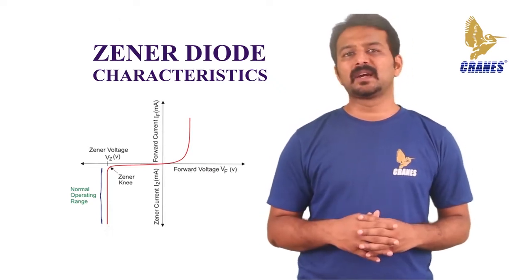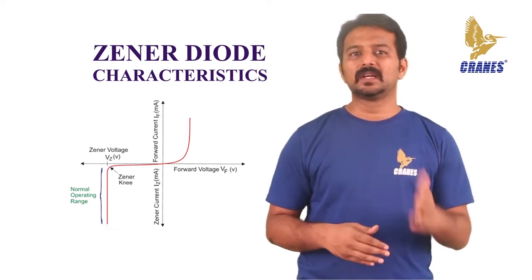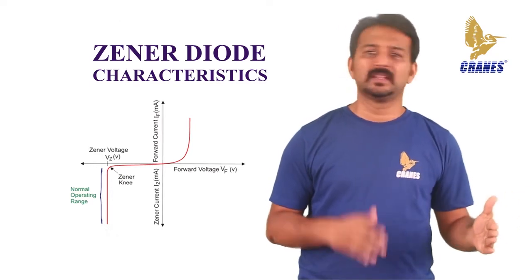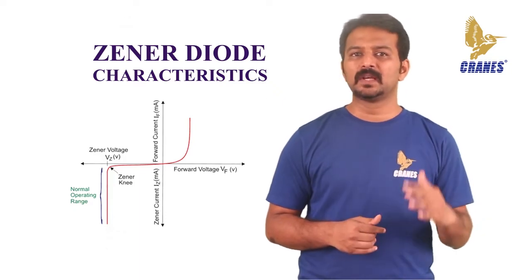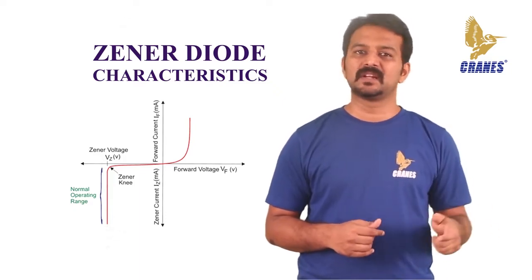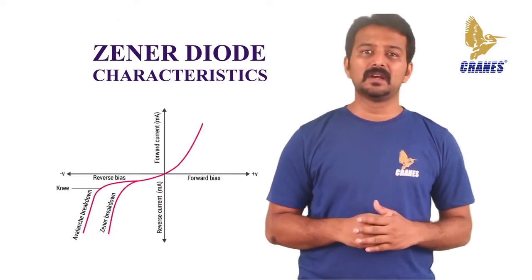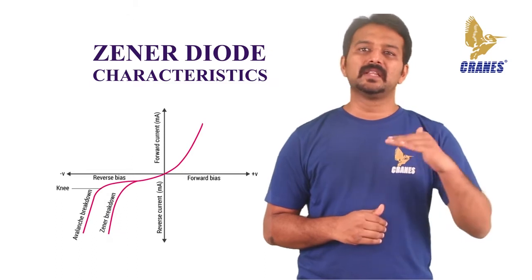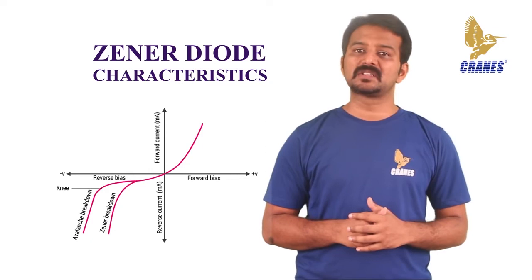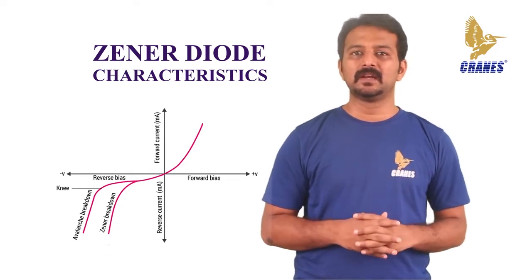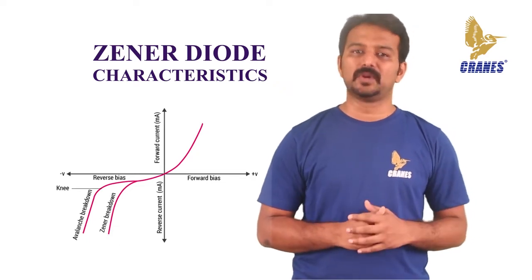However, unlike a conventional diode that blocks any flow of current through itself when it is reverse biased, that is, the cathode becomes more positive than the anode, as soon as the reverse voltage reaches a predetermined value, the Zener diode begins to conduct in the reverse direction. This is because when the reverse voltage applied across the Zener diode exceeds the rated voltage of the device, a process called avalanche breakdown occurs in the semiconductor depletion layer and a current starts to flow through the diode to limit this increase in the voltage.